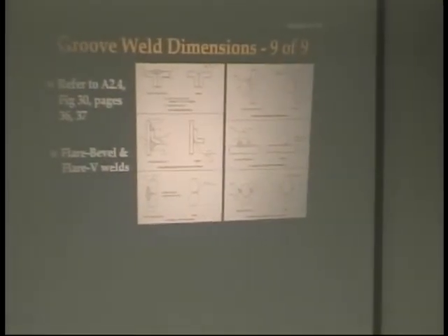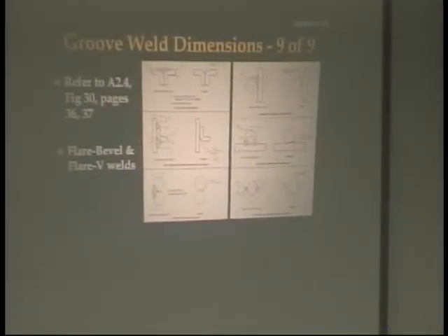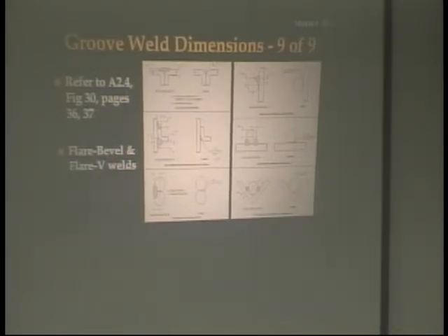And looking at that, if you read the notes, it says, variable E denotes the groove weld size. The depth of the bevel S equals the radius of the round member. So they can punch in whatever numbers they need to there to accurately account for the dimensioning of that. They've just substituted letters instead of dimensions in this example.